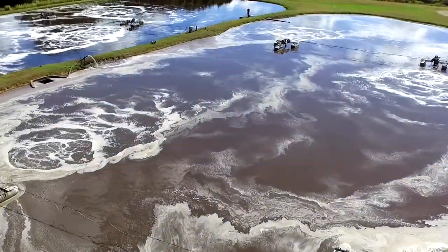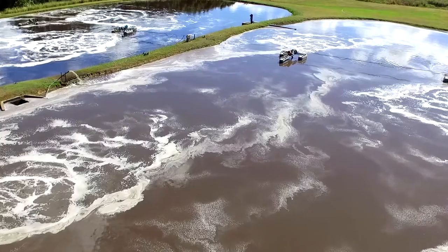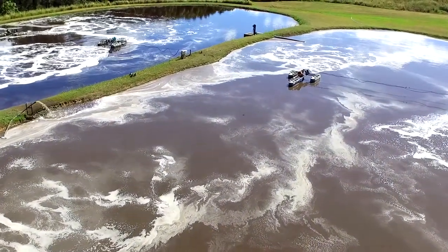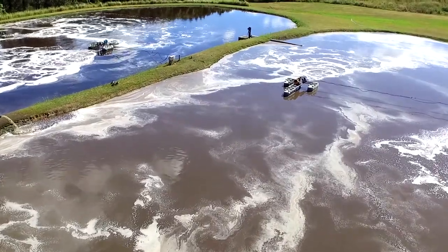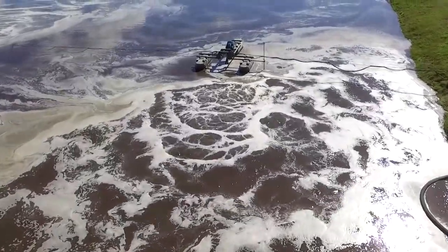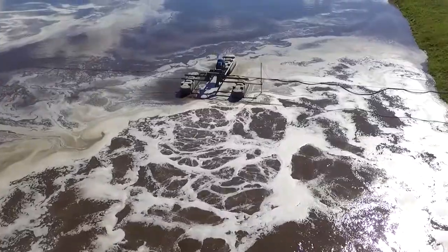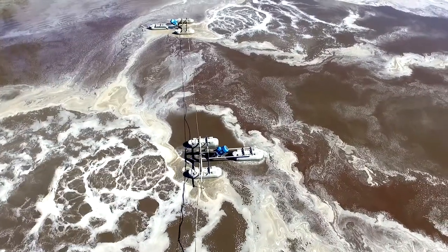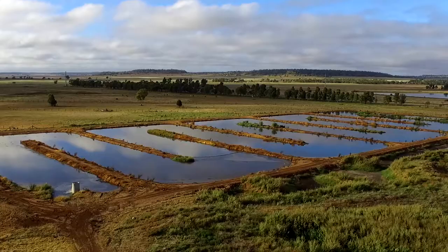Because aerated ponds are not dependent on less reliable natural or seasonal factors, such as algae, they are more effective at removing organic loads compared with facultative ponds. They are, however, more expensive to construct and have ongoing energy costs to operate compared with facultative ponds and can produce significant levels of sludge over time.